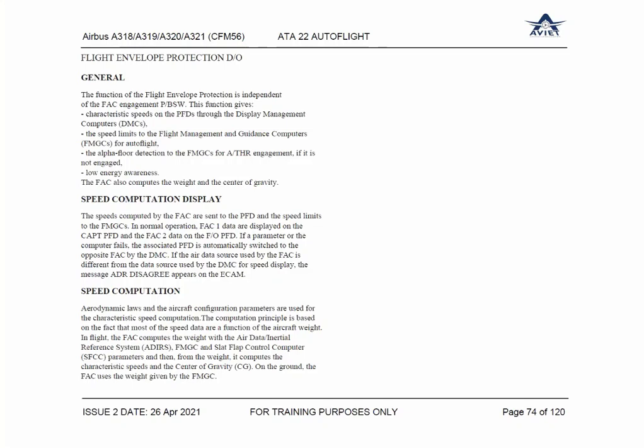Yes. So basically, the pilot gets the trim sheet. That load and trim sheet carries the total cargo weight. It carries the weight of the passengers. Correct. So this is the additional weight. Fuel and hydraulic fluid, they get the fuel figure, so they calculate the fuel weight also.